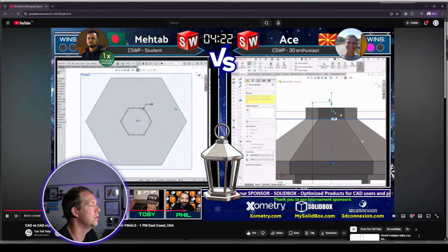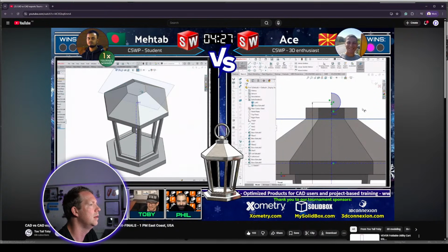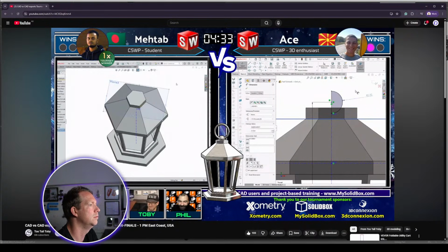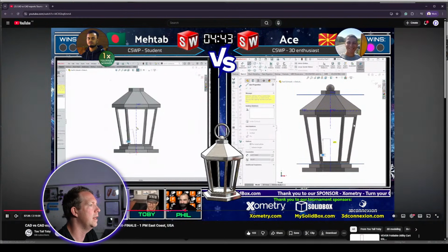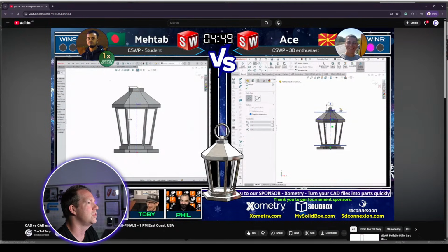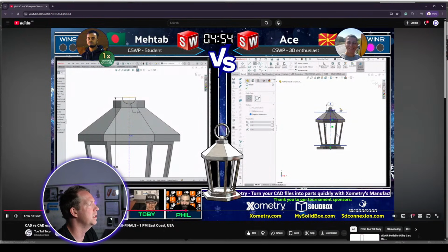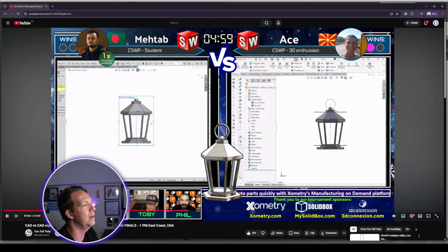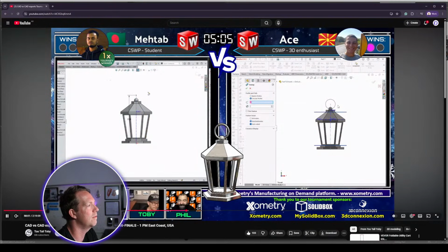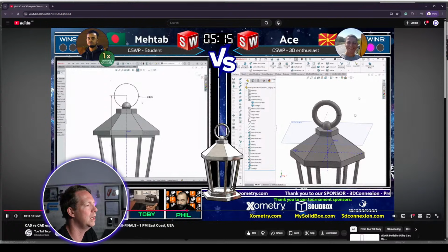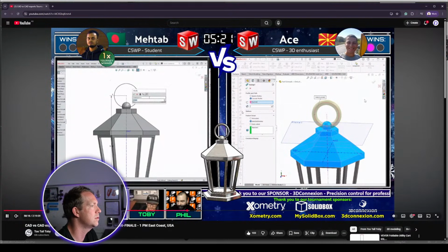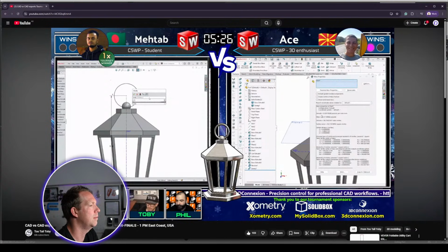Here, doing the dimensions for the 2 revolves at the top. Semicircle dimension from the origin, perfect way to do the sphere revolve. And then again, he's got another construction line for the last one. I think this was a really smart way to do it. I actually did this one with a revolve, I believe, but I think doing the sweep, I know you got the dimension wrong originally, but doing the sweep with the circular profile was really efficient there, and the best way to do it. And I think that answer was right.